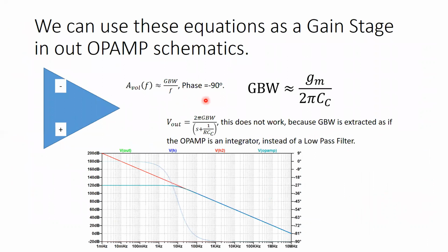All right. Now again, you're just designing a gain stage. You're an op-amp designer, all right, which again isn't this course, but just so you know, the gain bandwidth is really related to that feedback capacitor, and GM comes from the transistors.